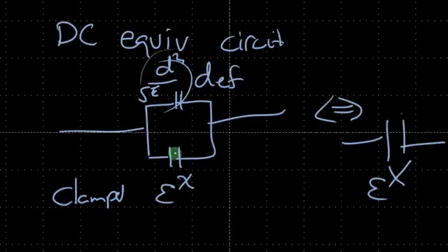But basically, what happens is you diminish the effect of this, because the effective compliance of the material gets larger as you are increasing the external material. And because the constraint gets larger, the material effectively feels stiffer and more constrained. Therefore, this contribution will decrease.